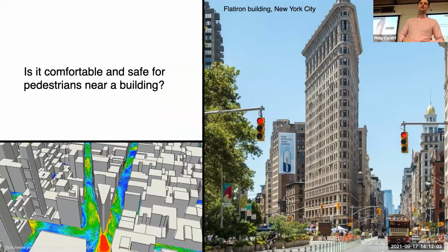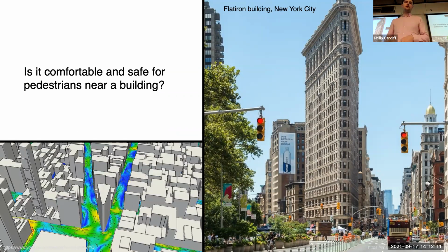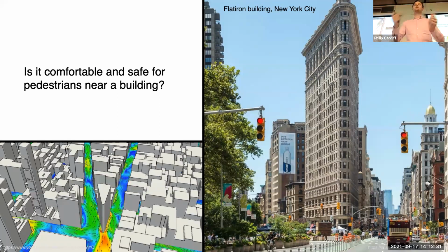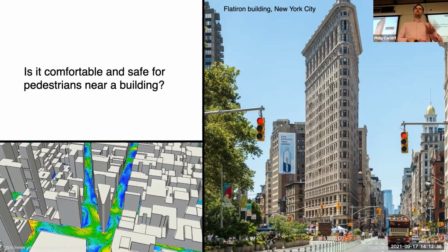In the civil engineering space, there's things like building comfort, or pedestrian comfort. So when large buildings are designed, and this is even the case in Dublin, if you have a nice little tree and a bench the architects put in for someone to sit at, well, nobody's going to sit at it if the wind's over 2 meters per second on average. It'll be blown all over the place. So there's a scale called the Lawson scale that will tell you people are happy to walk in this wind speed, they're happy to sit in this, they're happy to drink coffee in this, they're happy to do both in this wind scale. So when the architects come up with designs, they send it off to companies. There's lots from around Dublin, companies like Arup and other mechanical services companies like that. And they can do safety analysis, and they will say, well, it's actually pretty windy in this spot. We suggest you stick more trees here, or a canopy going down above the entrance of the building to divert the wind.